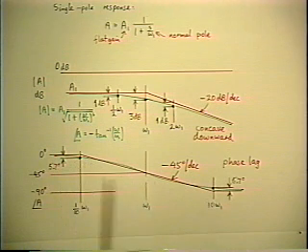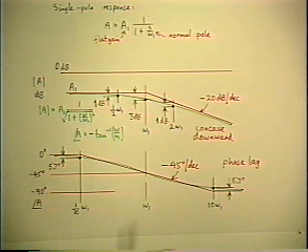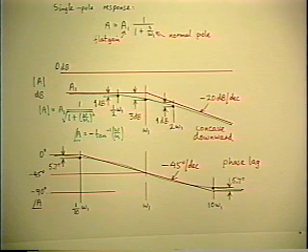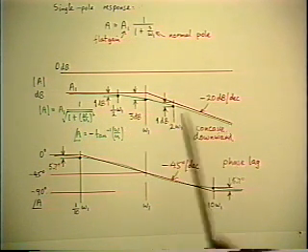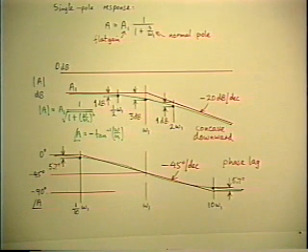So those straight lines are pretty good approximations for the phase function of a single pole. And that's usually sufficient to draw all the sketches you need, just as the asymptotes are sufficient for the magnitude function.